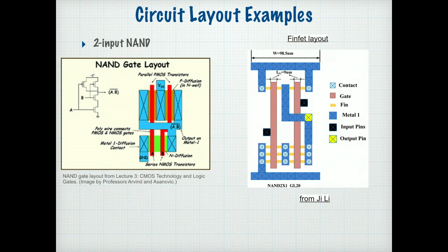But these 3 transistors are all in parallel with one another, so they're all acting together. They're effectively acting like one wide transistor, as we would see in a planar process. So these are the kind of layouts that would come as part of the standard cell library in the ASIC design flow, and then would be used for generating the masks of the final layout.